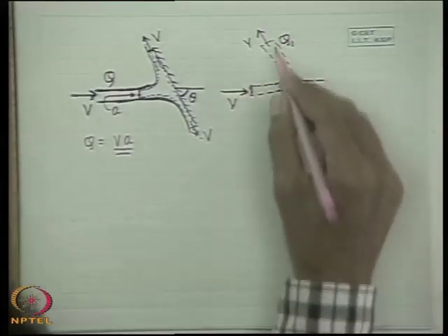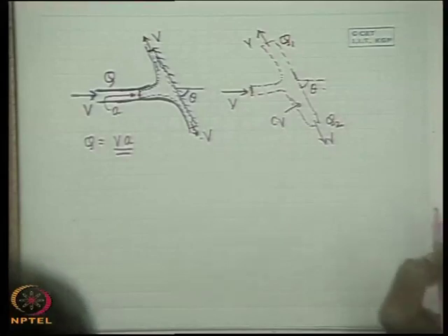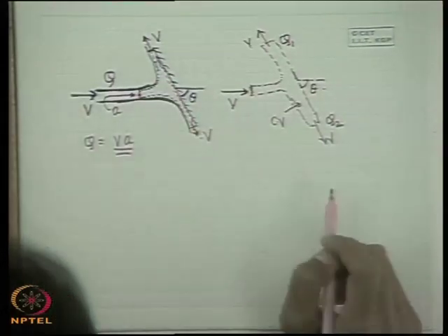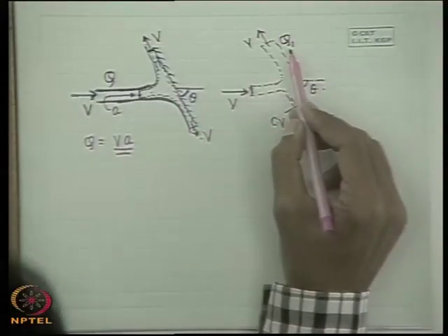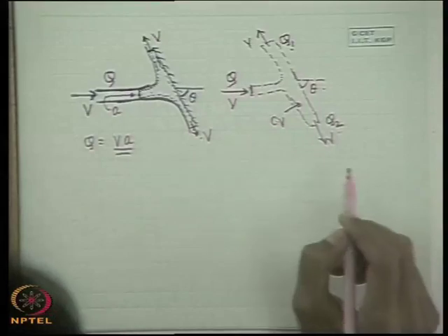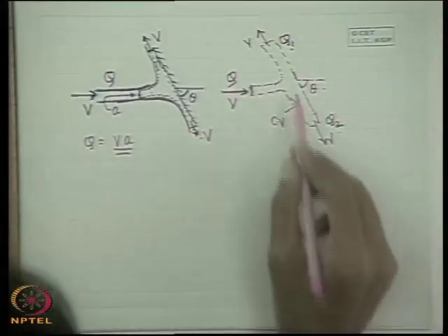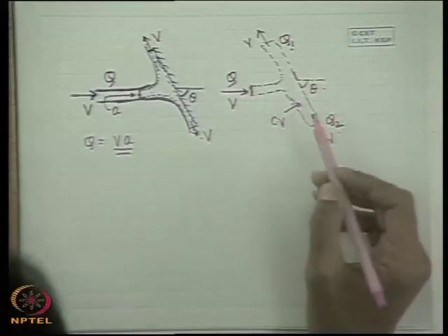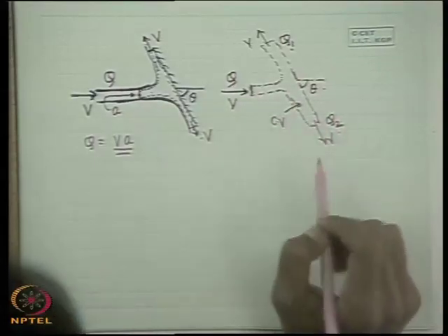Let Q1 and Q2 be the volume flow rates through these two paths, which is being divided after impinging on the plate. First of all, we will find out a relationship between Q1, Q2 and Q through the application of the momentum theorem to the control volume, and also by the application of the same theorem to this control volume we will find the force acting.